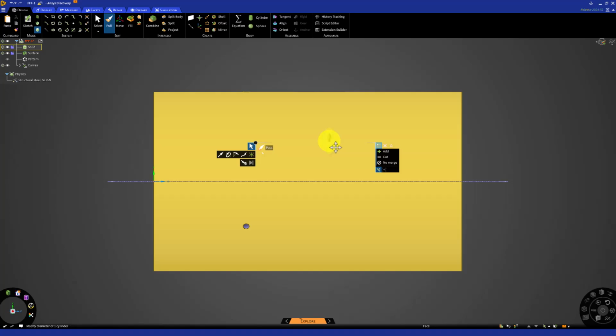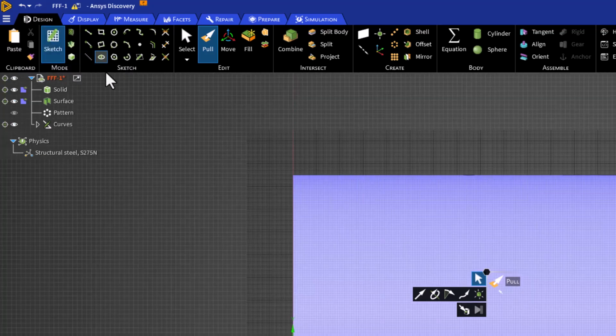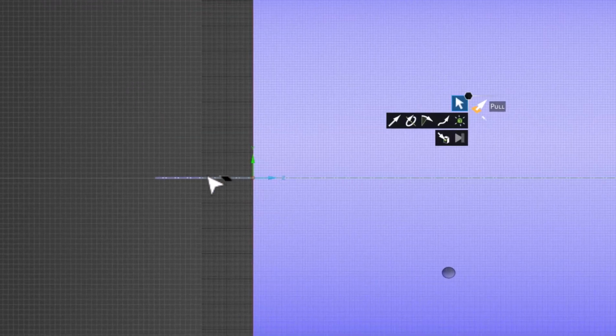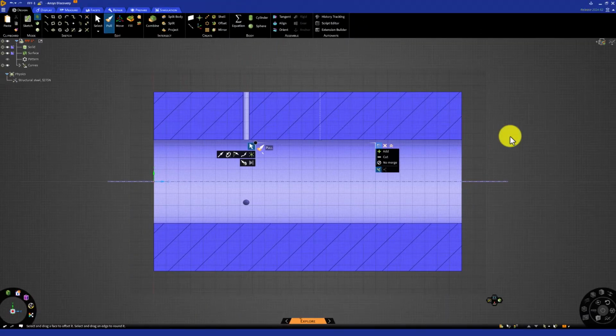To fix this, select Section Mode in the top bar and click on the x-axis to view the same cross-section we were sketching on. This allows us to better view and manipulate the surface to create the obstruction. Again, press V on your keyboard to orient the view to be facing this plane if the orientation got altered.